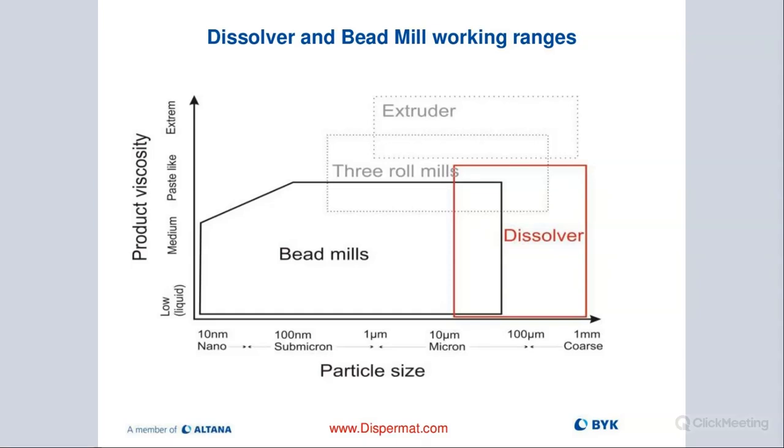Here you can see just kind of like the breakout. So again, it's about 10 microns of particle size. When we start moving over to the bead milling process, probably 10 to 20 microns is usually a rule of thumb. And then with the correct type of bead mill, we are really able to produce very, very small particles in the submicron range. We can go all the way past 100 nanometers. It is not uncommon for certain specialty coatings, like automotive applications, for example. They are really looking for super small particle size due to the finish that they require.